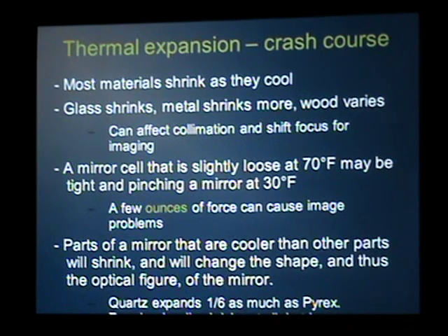Also, metal shrinks, but more than glass. So if your mirror is in a tightly fitting metal cell, as it gets colder, it's going to get more and more pinched. Or it may go from loose to pinched.